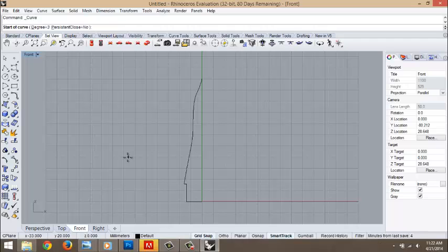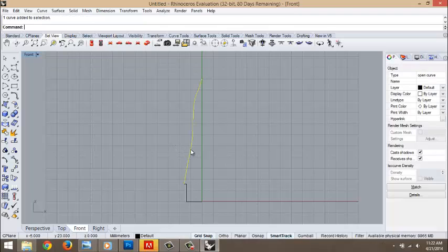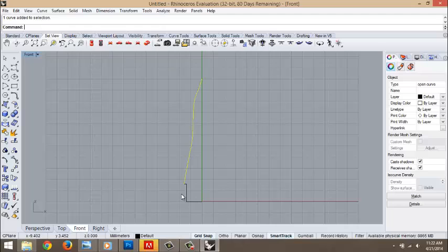The next thing I need to do is to attach these two lines to each other. Oops, I'm going to select them first, so I need to go up here to grab them. So I have an arrow key now. I'm going to use the shift key on the keyboard to select, or hold that down, select one line. Then I'm going to select the other line, holding the shift key down and clicking on the mouse left key. Both lines are selected.